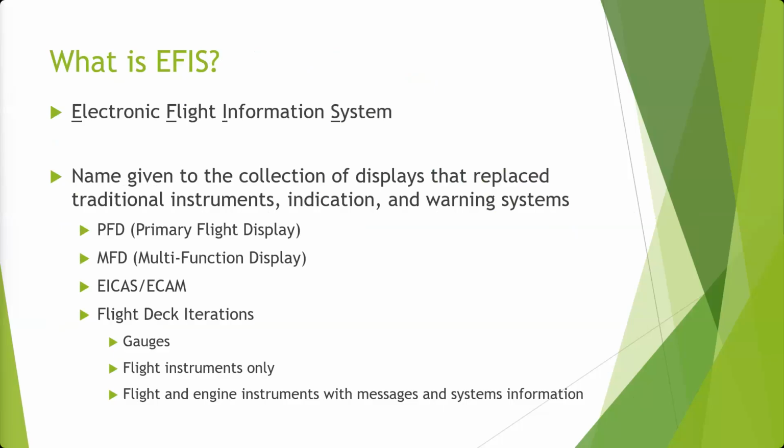So this is going to replace what's called the six-pack, with typically most aircraft having two displays: a primary flight display and a multifunction display. Usually on most of these aircraft, the primary flight display has the artificial horizon. There's the one I was looking for. That's your attitude indication. On your primary flight display, that one usually has airspeed, altitude, and that artificial horizon that shows your attitude. Sometimes it has a turn coordinator. The multifunction display often is used for the navigation instruments. That shows your heading, your VOR, your localizer, those kinds of things. So that's the normal display you'd have on those.